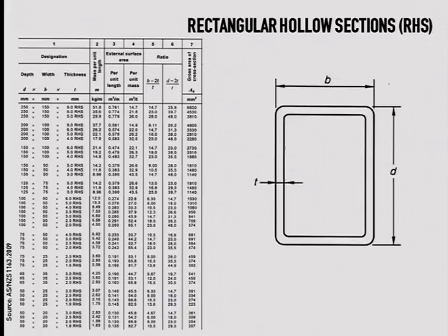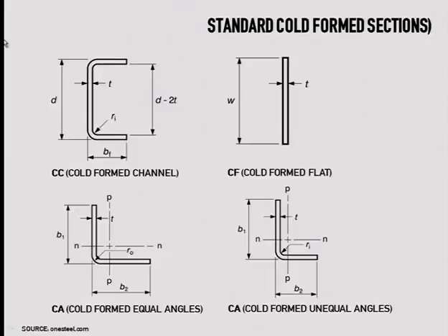Rectangular, and yes, here already you see that there is the parallel flange but the cold formed one. So you see the difference. Because of folding, this one is not straight, there is a little bit of fillet. So that's the way to recognize how similar profiles which perform similar tasks can actually be shaped slightly different. So you will be able to recognize cold formed and hot formed by means of that.